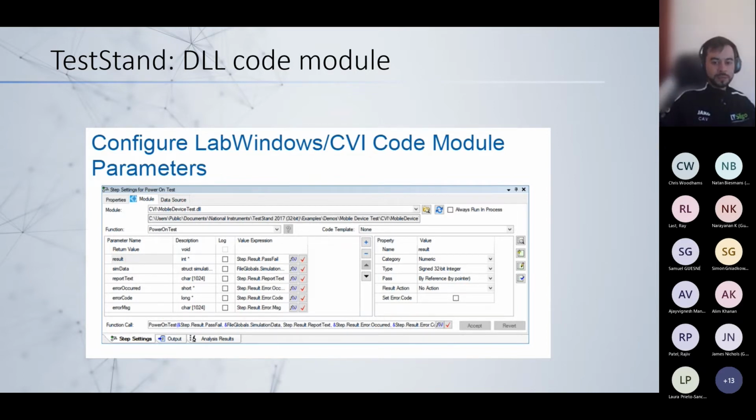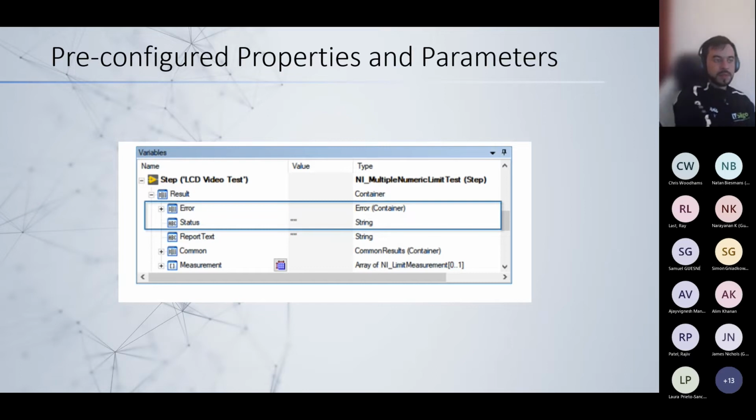The good thing also that we achieve in TestStand is the commonality of some parameters. So how you capture the error, where the error goes. There's always a receptacle for error. What's the status of that action step? Was it pass, done, error, skipped? That's always standardized lingo in TestStand, and much more. You can log more parameters. You can even log requirements, which is going to tie them up with the results. That's always nice to explore, the extra properties which are common.